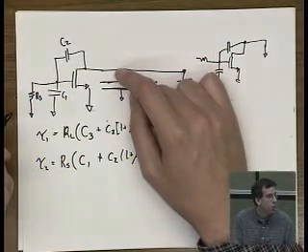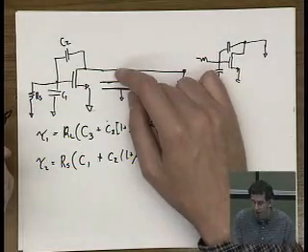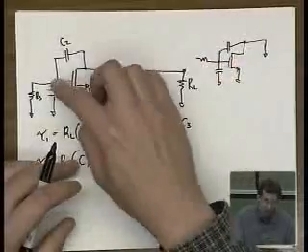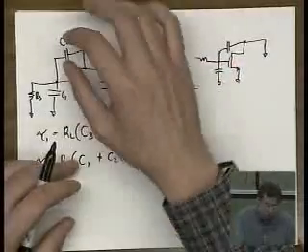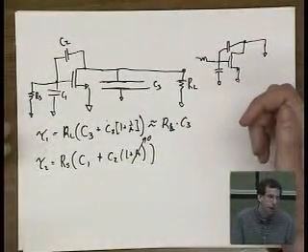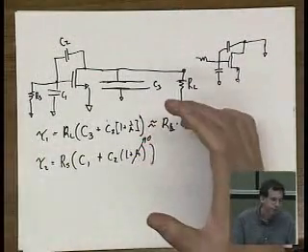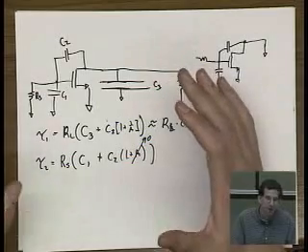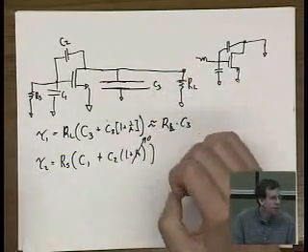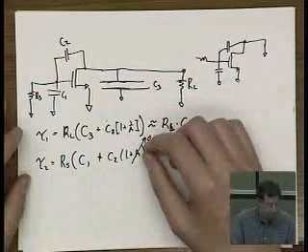In reality, there will still be some residual Miller effect, and there will be some complex impedance here, so you'll have some gain from input to output. So this capacitor will sort of look bigger, but we're making approximations to keep the mathematics of the interaction relatively straightforward.